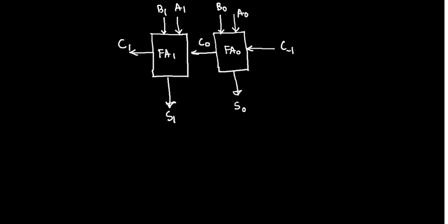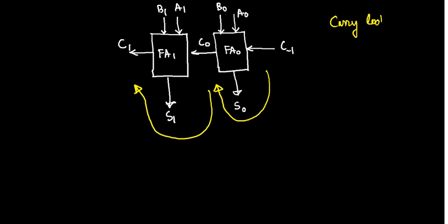Say for example it is a large bit addition, like 32-bit or 64-bit, and the processing speed is very high. So we are very concerned about this carry propagation delay. The delay required to propagate the carry from one stage to another is called the carry propagation delay. The further stages can't calculate the sum and the carry unless the carry from the previous stage has arrived. To solve this problem, a circuit is proposed, called the carry look ahead adder. Carry look ahead circuit is proposed.